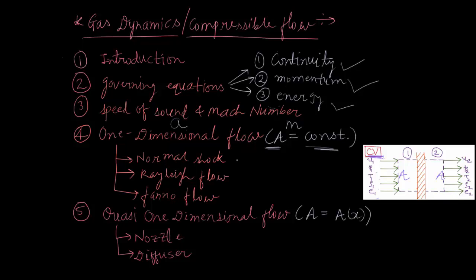And that something can be normal shock wave, or the flow with heat addition, which is called Rayleigh flow, and the flow with friction, which is also called Fanno flow. We will see all these three phenomena in detail.